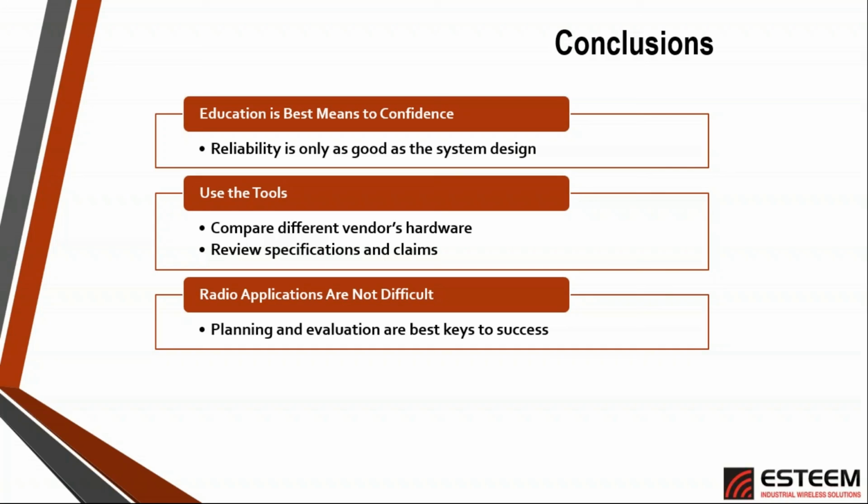We want you to compare the different vendor hardware so that if you're seeing something in a specification sheet and it doesn't necessarily look correct, you're welcome to look at these tools and say, oh, okay, that's actually where the problem came in, or that's how they're making this claim. Because radio applications themselves are not difficult, but they are somewhat unforgiving to small problems. So the planning and the evaluation are the key to success.